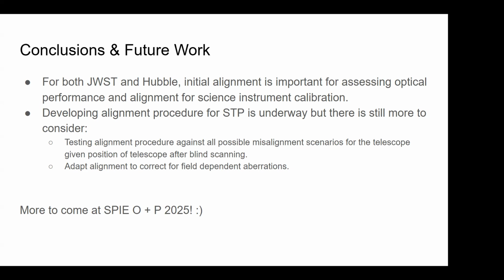We know we probably need to use temperature telemetry to make focus corrections, maybe on a 10-second cadence, rather than just waiting on the 60-second phase retrieval. But that's complicated, because focus is drifting during a measurement. Is it purely a correction, or also predicting based on telemetry? We would probably have to do some predictive.